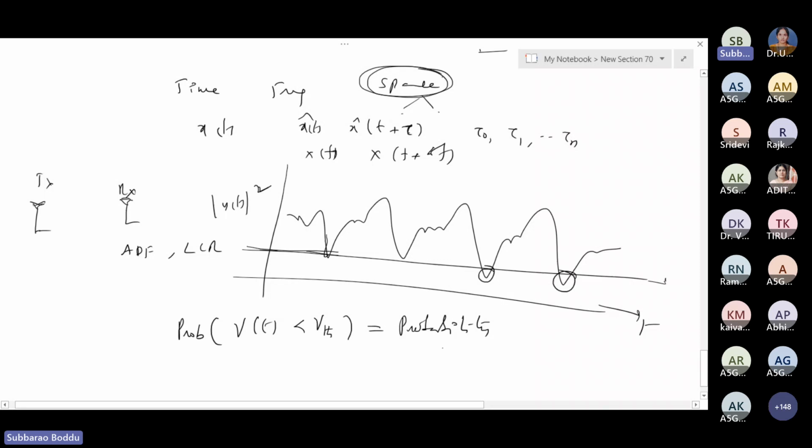This is actually designed. To want this probability low, what we do is increase the level of the transmitter. When I increase the level of the transmitter, it would be like this, the channel variation goes like this. We increase the level of the transmitter so that my received signal strength is increased, so there is hardly any probability that the signal goes below the threshold.